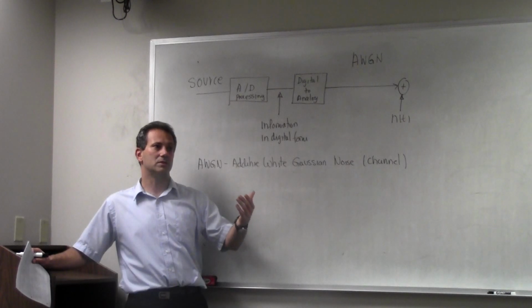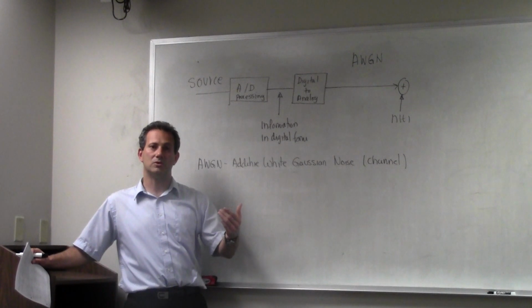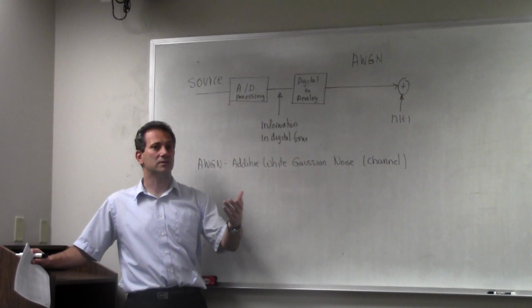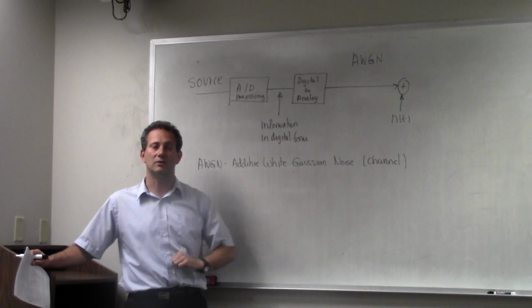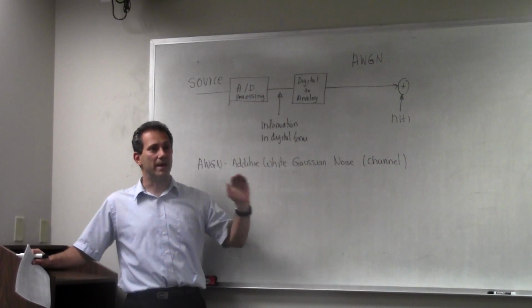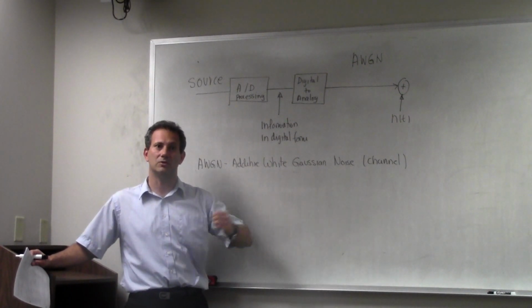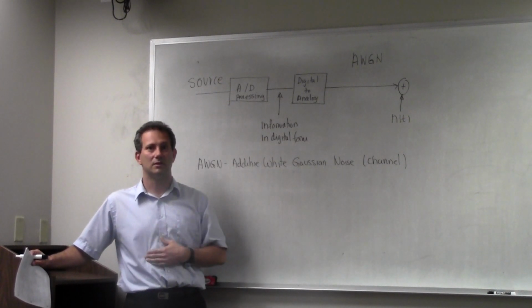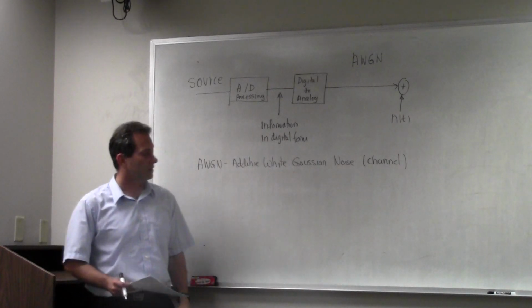How do you get that noise? Let's say you take the thermal noise and you run it through a filter. Because it goes through a filter, it's not white anymore, right? Its frequency domain characteristic, the power spectral density, is not uniform. It goes to 0 after the cutoff frequency of the filter. In the amplitude domain, when you filter Gaussian noise, you end up with Gaussian noise as well. So this would be Gaussian colored or band-limited noise. So this is what all of these things mean.